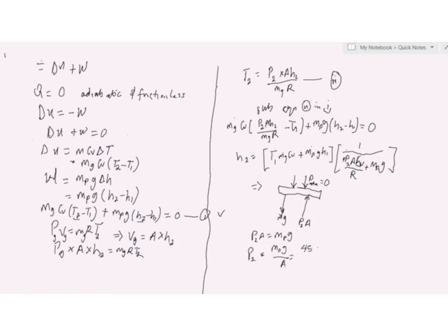45, given from the question, multiplied by 9.81, all over the area, also given from the question to be 50 times 10 raised to power minus 4. So this is equal to 82.29 kilopascal. So with this pressure we can use it to obtain our H2.